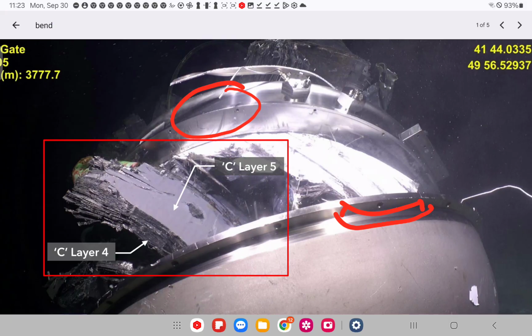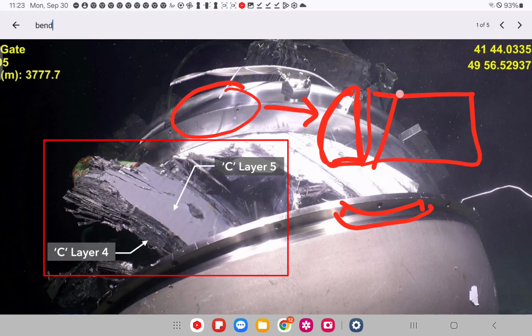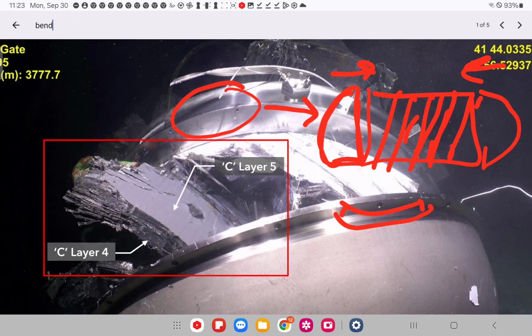They go inbound, and the front nose cone is still under pressure from the outside, trying to close in on the hull all the time to try to buckle this area here. All right, and then the rear is doing the same thing. It's trying to buckle the same area. That means it's trying to crush in and crush in. But the carbon fiber, being a solid outer tube, if you will, solid material, of course composed of layers, can resist the buckling, the inward pressure that's being applied.